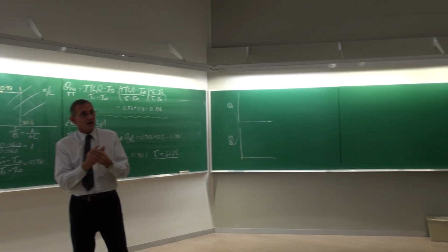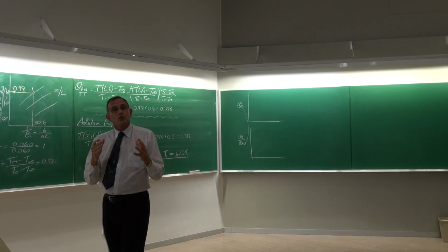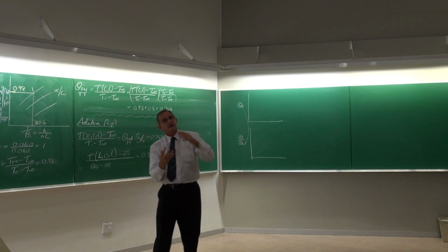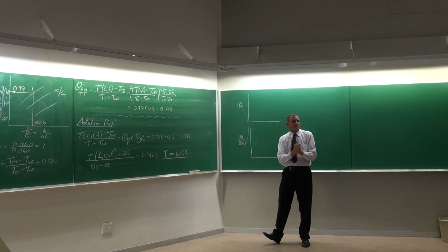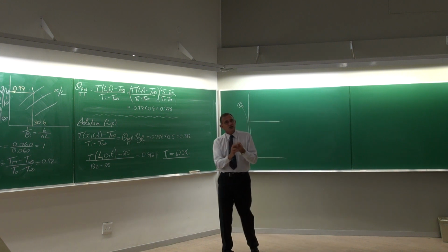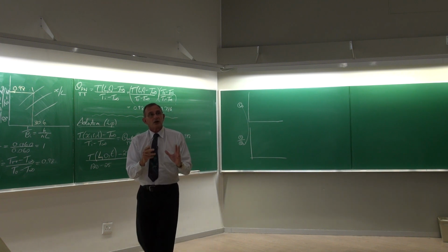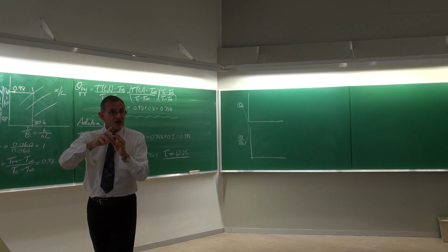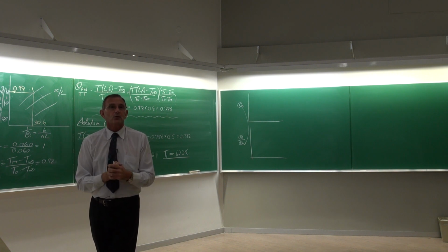With the equations, just coming back to them, remember the first set of simplifications would typically be where x is equal to 0 and r is equal to 0. And then they've given a set of equations which are all in the center, and where the non-dimensionalized time is larger than 0.2. So that's the simplest equations. The next set of equations were for when it was not on the center line. Then you need to take into consideration an extra cosine term, or the Bessel function term. Okay.